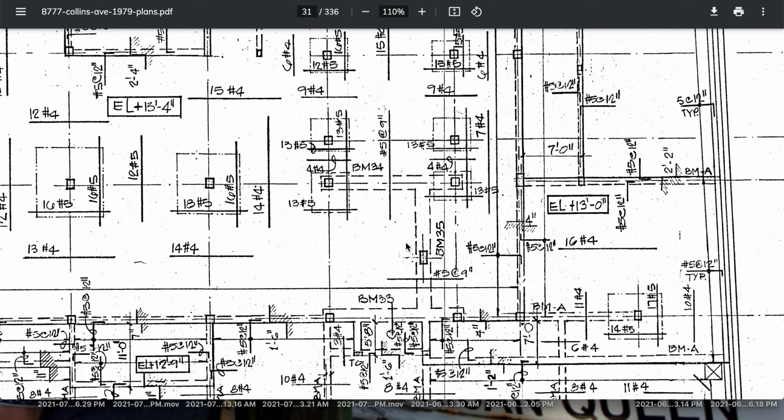That's testing. So here's your transfer beam again. So what is a transfer beam? It's going to transfer the load down here and down here. These guys are just straight down. But this is the opening that they wanted, and this gives them that. This allows them to still run columns, but then this would be a bigger beam. That's what I'm thinking is going on here, for that bump out of the structure. But proving the bump out of the structure is very difficult, right? Because I don't really have close-up images like that to show the step back.